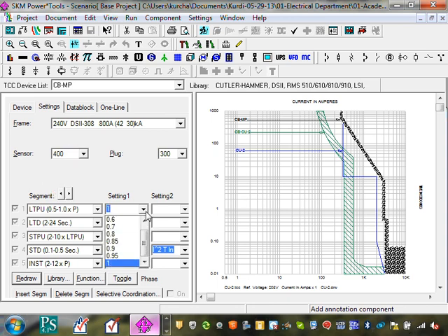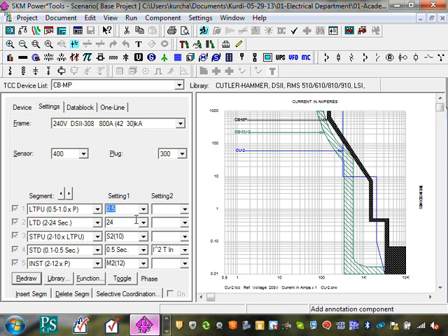If I set this one, can you guys see the settings here? You can set it at 0.5. Now this 300 circuit breaker has turned into half of this, because I set it at half, so that will be 150. Just by tweaking the dial, I have turned the circuit breaker into a 150 circuit breaker. What they do here is take the 0.5 setting multiplied by this: 300 multiplied by 0.5. Now, just by dialing that thing, you've got yourself a 150 circuit breaker. Very, very dangerous to mess with.